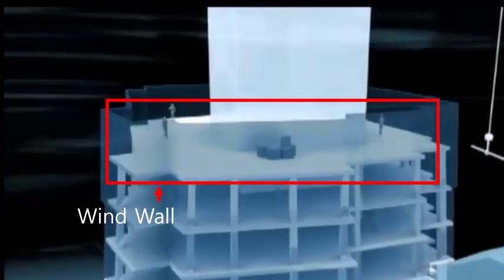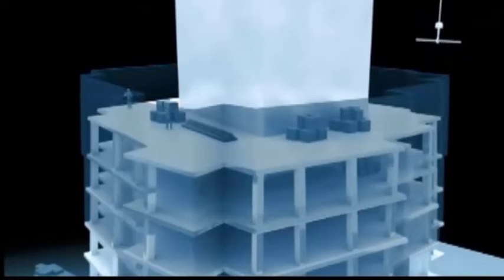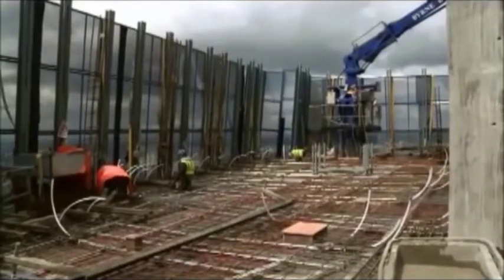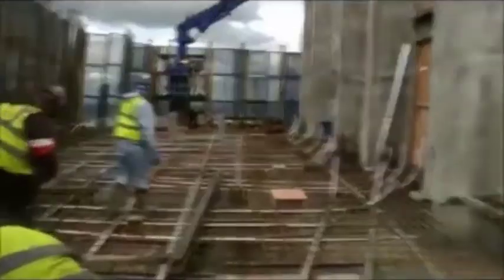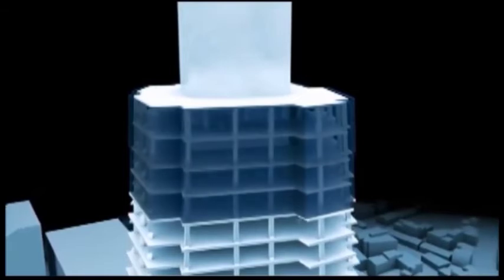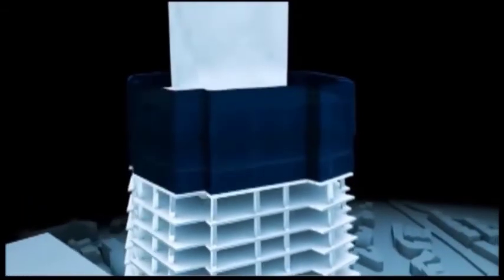In pre-tension concrete floor, to prevent wind during construction of floor, constructors installed 3 meters windwall first. Next, steel cage is installed and concrete poured, so column is made. Next, floor concrete is poured. It took 20 hours to harden enough. Each floor is finished in 6-day cycle and process started again.